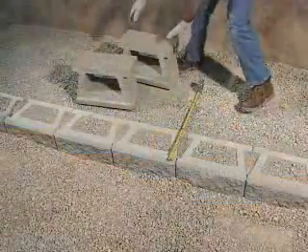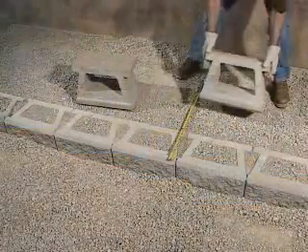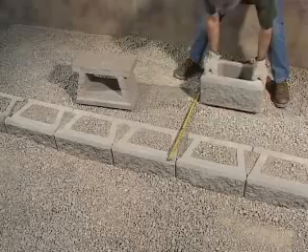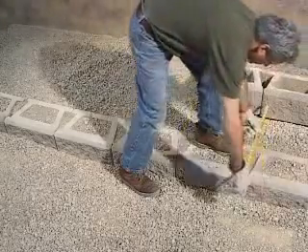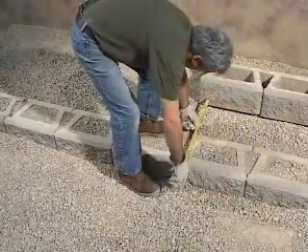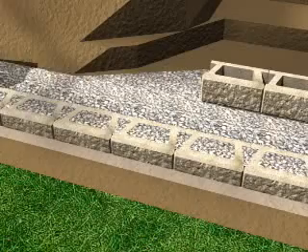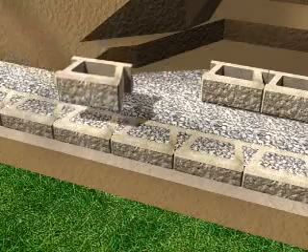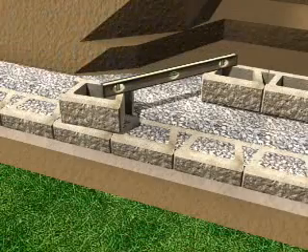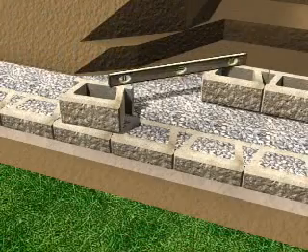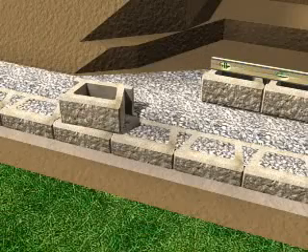Measure the distance for the next stair riser and place the blocks, making sure to allow for 6 inches behind the block. Measure the distance between the stairs to make sure that the blocks are parallel with the stairs in front. Place a temporary block on top of the wall close enough so that you can place a 4-foot level from the block to the stair riser block. This will ensure the stair riser blocks will be level with the rest of the wall. Then level and adjust the rest of the stair riser blocks.